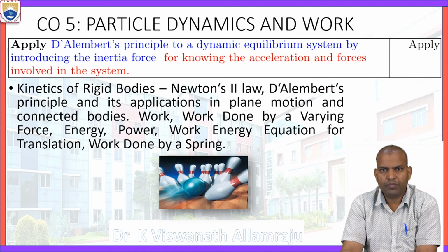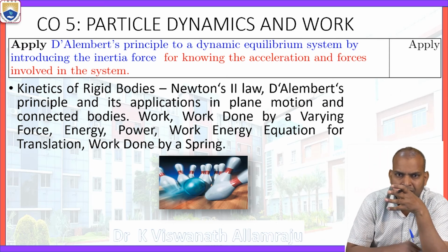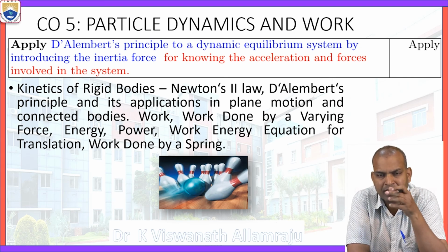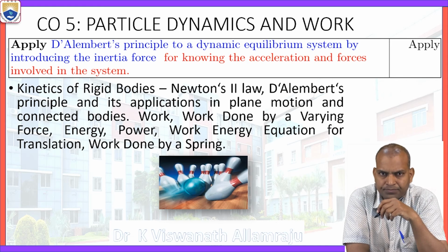And also free body diagrams for dynamic forces. What we have to make is that the system is under dynamic equilibrium. That means we have to draw the free body diagram and apply D'Alembert's principle in such a way that we can write the equation, that is the characteristic equation of a system.